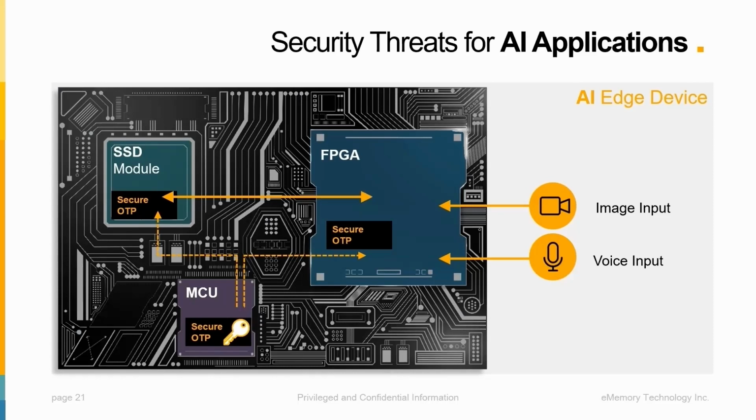Therefore, the integrity of an AI model must be protected through secure boot and authentication for each connected module. And each module must also have a set of authentication keys to be stored in the board manager, which controls the secure boot process. To answer this need for a secure boot process, we will need a device that can identify itself from others with a unique PUF code while storing this key information in a non-volatile memory, thus calling for a need for PUF-embedded NVMs.